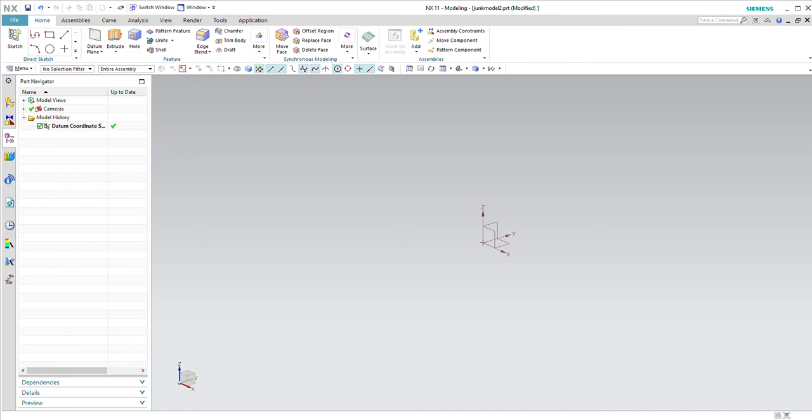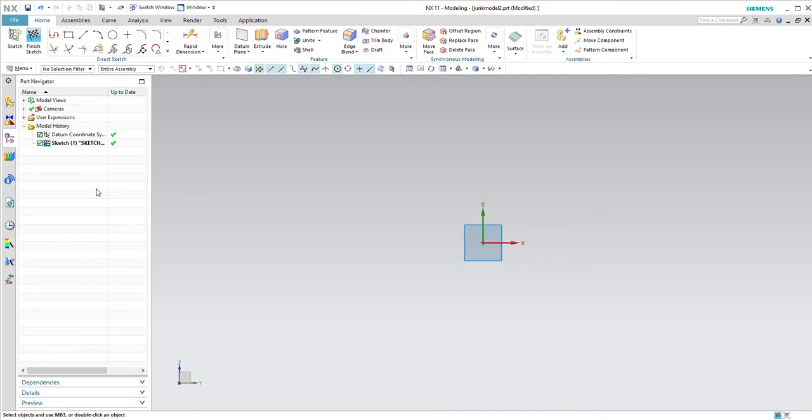In order to create a structure, you're always, or most of the time, going to create a sketch of some structure. So I select sketch. I'm going to select the plane just by hovering. So I'm going to select the XY plane and say OK. Now it will orient me to that sketch, and I can draw whatever I want to draw, different shapes. That would be the profile of the object I'm interested in.